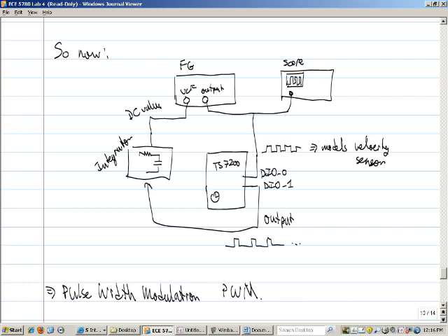So what it should decide is, what do I need to do to bring the frequency down by 200 hertz? How do I calculate that in terms of a duty cycle? And that gives me what change in the duty cycle I need to make. I send that out to my integrator circuit, producing a DC value that will apply to the VCF input that will alter the frequency that the function generator is outputting and will bring me down to 200 hertz.